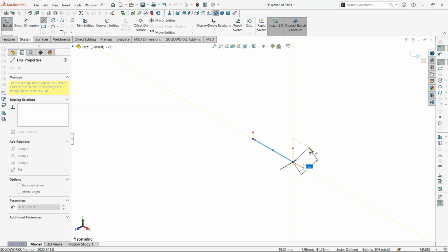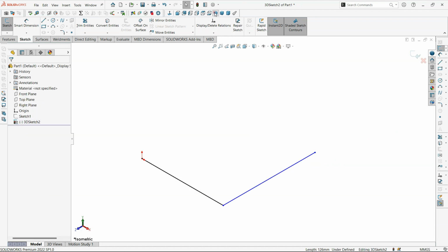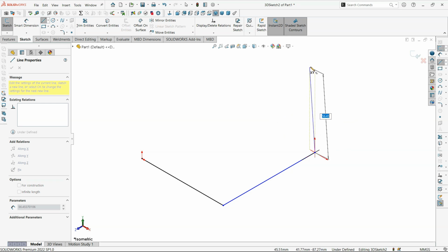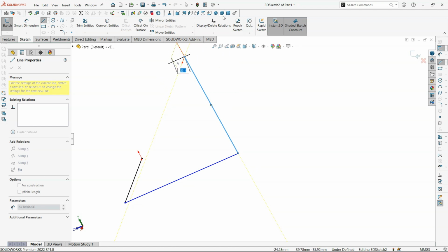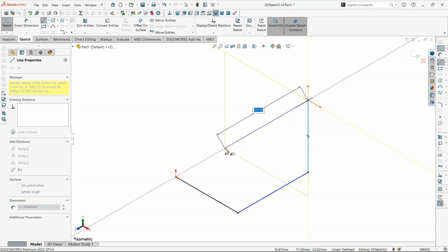Now I want to move to this plane, and I will just do this. Now you see, by clicking on Tab, I have entered the YZ plane. That is, we are going backwards now. So I have gone backward. Now I want to go upward. Let's check the look. You see, it was not the image I wanted, so I will just click delete and click on isometric view, and again start sketching. So I want to go upward now. I have pressed the Tab key, and now you see it is going upward. So it is currently in the XY plane now.